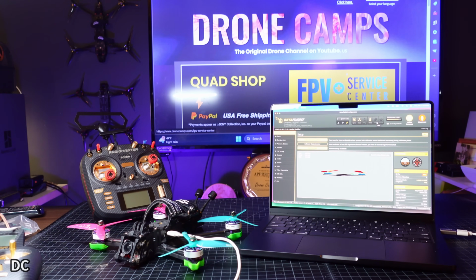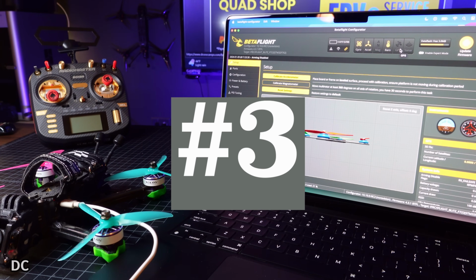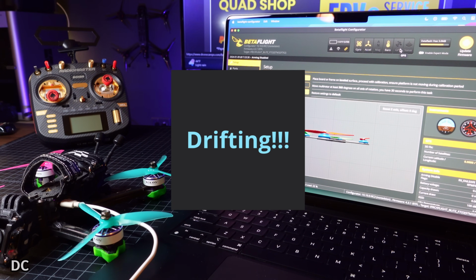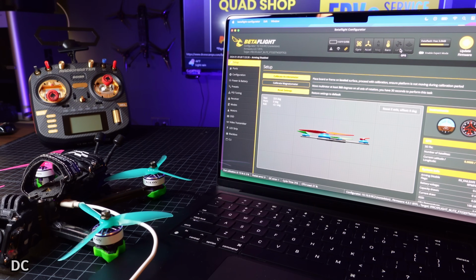Now, another common problem is that people say that their quad drifts one way or drifts the other. One of my biggest advices to you is not to do any trim on your radio.